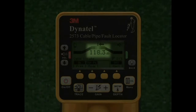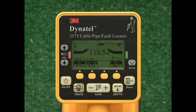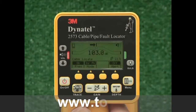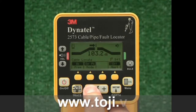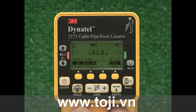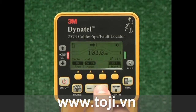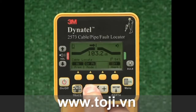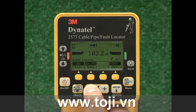The numerical signal strength in the middle of the locate screen indicates the actual strength of the transmitted signal that is reaching the receiver. The point at which this numerical signal is the highest value indicates the center of the electromagnetic field, or the target conductor. The bar graph should open when the receiver is off the target path and close when over the target path. If the bar graph is not responding to the target conductor, adjust the gain by pressing the gain adjust keys. In addition to the signal strength and the bar graph, the audio response of the unit will increase as you get closer to the target path.